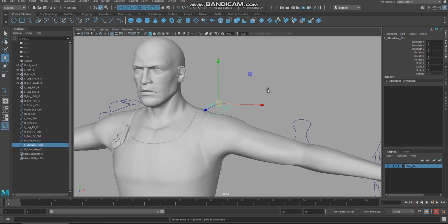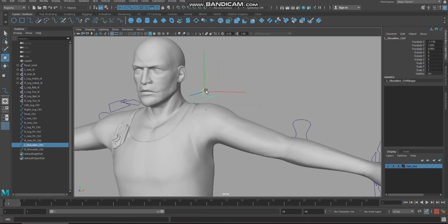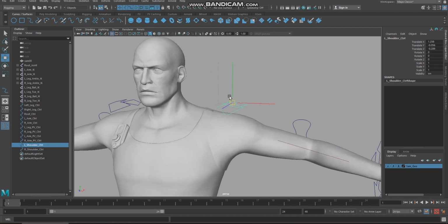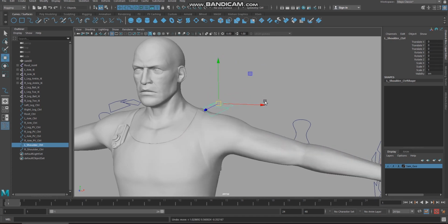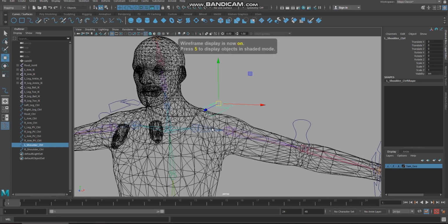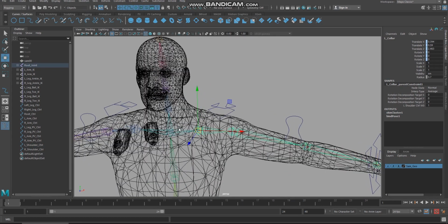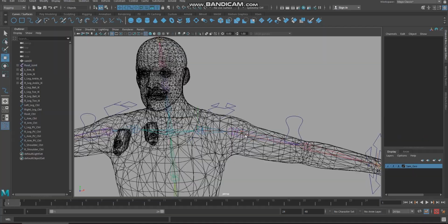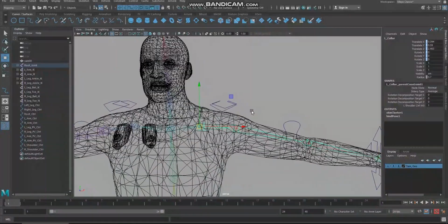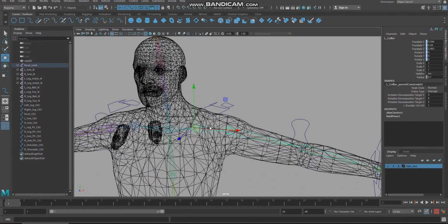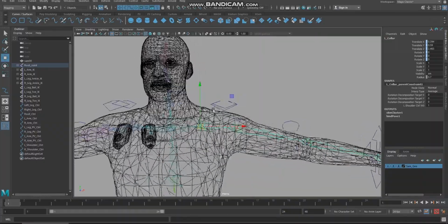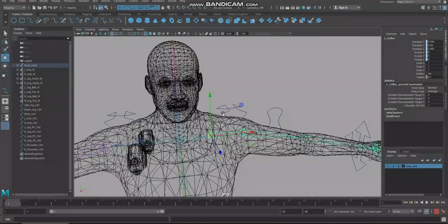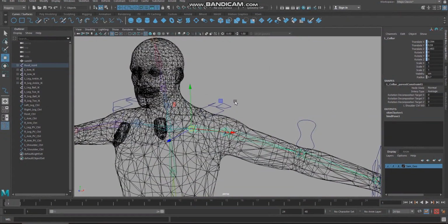See here you may have a doubt. You can watch the face of this character. If I move this, the face is also getting a little bit disturbed. That is because the influence of this bone or this bone are not properly painted. It is not properly distributed. So for that we need to select this bone and select the area which it should control and give some influencing. That is called paint weight tool, I told you earlier.